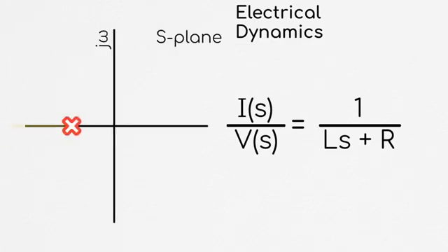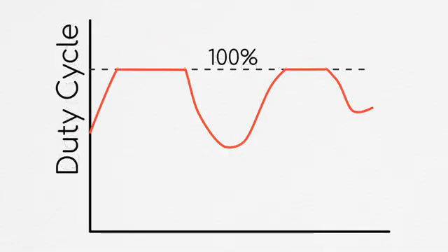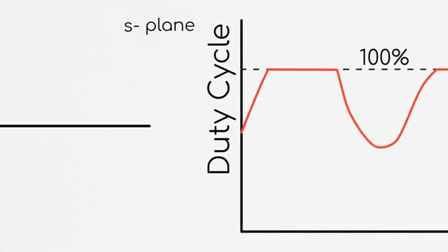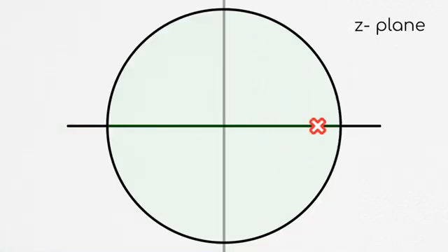Looking at the root locus, we see that since we only have the one real pole, we could in theory just use a proportional controller here. And as we crank the gain up, this pole will shift left and our system will respond quickly. However, there's a few practical issues with this. First of all, the voltage we can supply will at some point saturate, and then we'll have a nonlinear system. Additionally, since, like most real control systems, this is a discrete system, not a continuous one, if the proportional gain is high enough or our sampling frequency is low enough, it can result in instability.